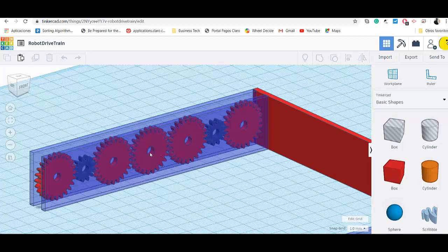The motor will go in the middle, and the output will be on these two gears at the end. Since they have the same number of teeth, it will cancel out. For example, I have 24 teeth on this one. With the 24 tooth, it's 1/1. Now, by one rotation of this one, I will have 2 rotations of this one.